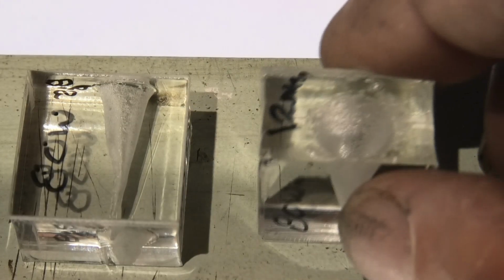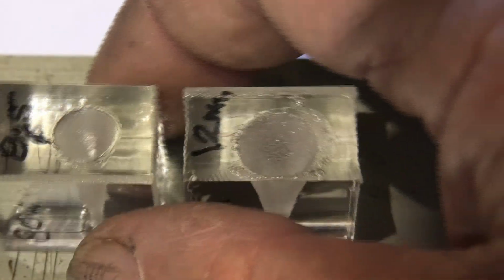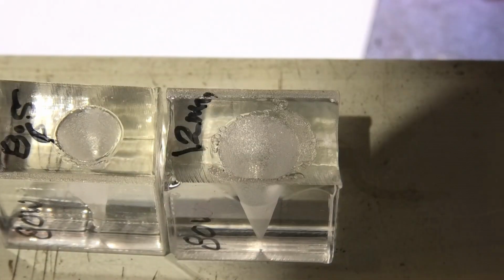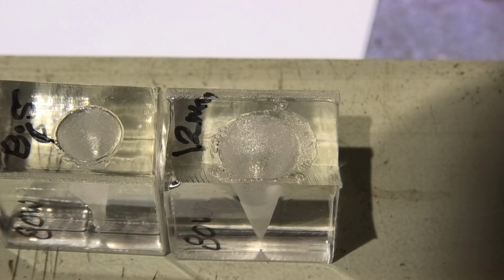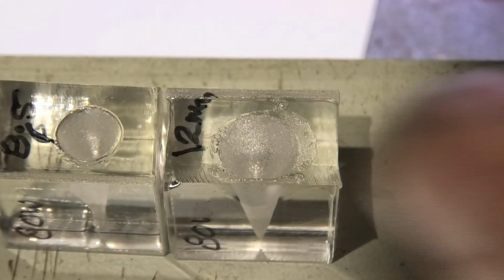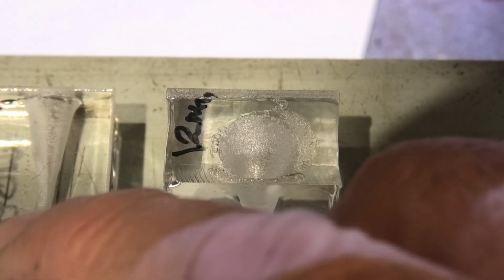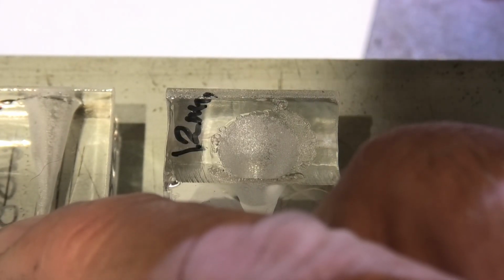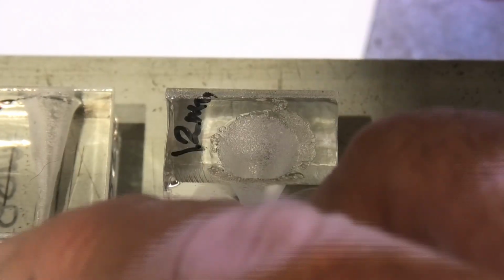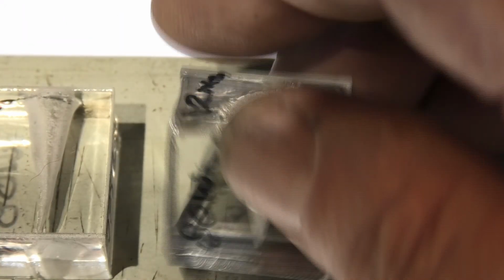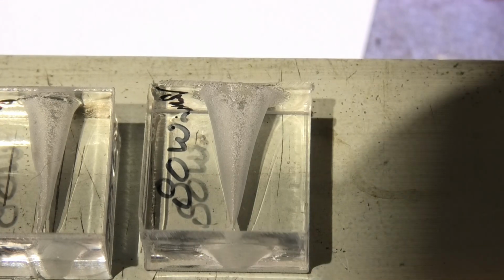Look at the size of this one and look at the size of this one. Because the beam size is smaller, remember the rules about a Gaussian distribution? If the beam size is small, for the same amount of power, we shall have a sharper beam. And a sharper beam means we basically have more intensity at the center and it cuts faster. So this one cut through in 12 seconds. This one took 30 seconds.